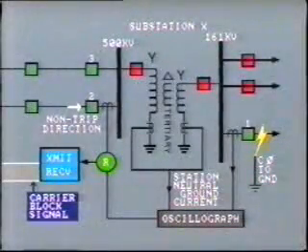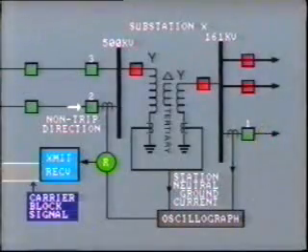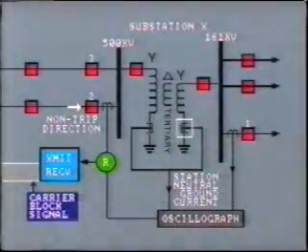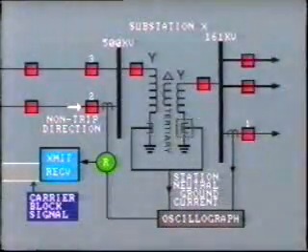As before, this was a temporary fault, so all breakers reclosed successfully at high speed. The problem was solved by replacing the 161 kV neutral CT with one having better operating characteristics. There are 2 basic methods for gathering fault data: automatic and manual.